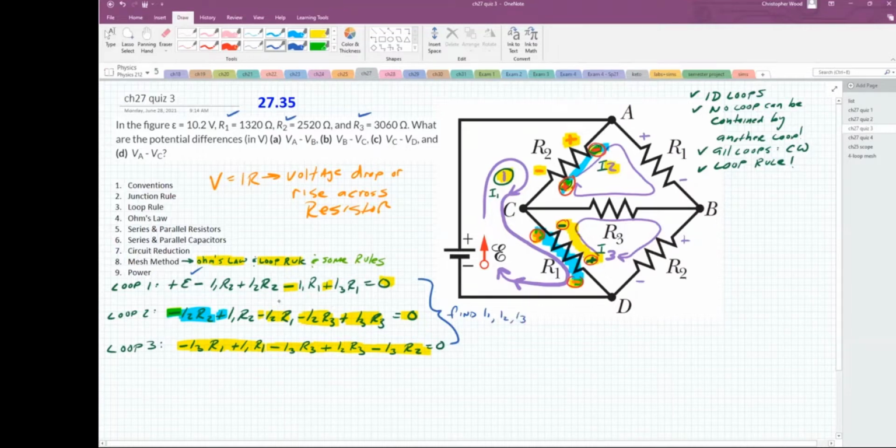And you would say, of course, Chris, because you basically have three unknowns and three equations. Remember that from algebra? You have three equations, the loop 1, loop 2, loop 3 equations, and across these three equations, you have three unknowns. What happens though, like exam 3 is here, and this is a 3-loop circuit. You're going to have a 5-loop circuit. That would take you the better part of a morning to figure out if you had to do that. So we're going to use a spreadsheet to do the dirty work for us.